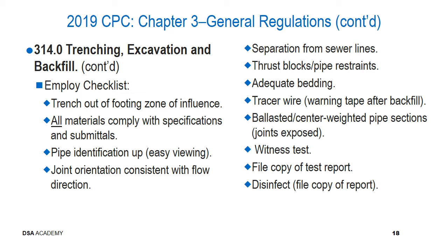For instance, the CPVC pipe that has been installed and the valve that we saw was installed. Those were delivered on the site well in advance of being used in the trench. So upon arrival, you want to make sure and check that those materials comply with the plans, then the specifications, and then the approved submittals. And you're going to document your approval of those items as was previously discussed in one of the administration sections of this training.